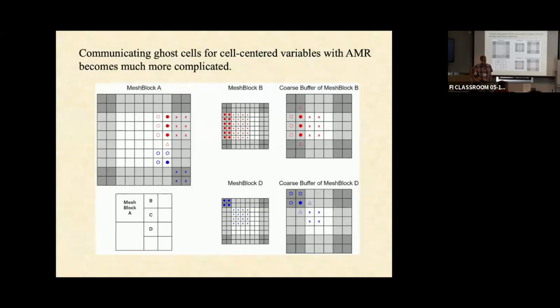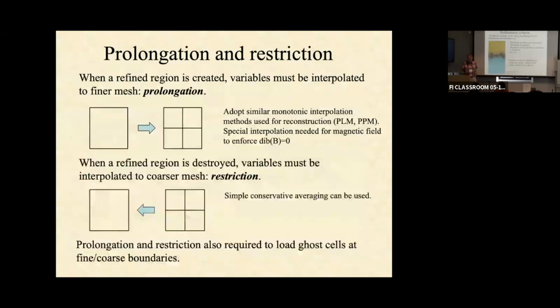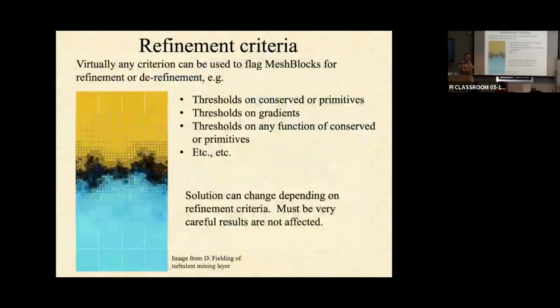Right. And what kind of test can you do? Yeah, I mean, I go back to this slide here. It's the same point I was saying here. I mean, forget about AMR. Just use a uniform mesh. How do I know my resolution was good enough that I have the right answer to whatever thing I just computed? I mean, this is the whole issue of convergence testing.